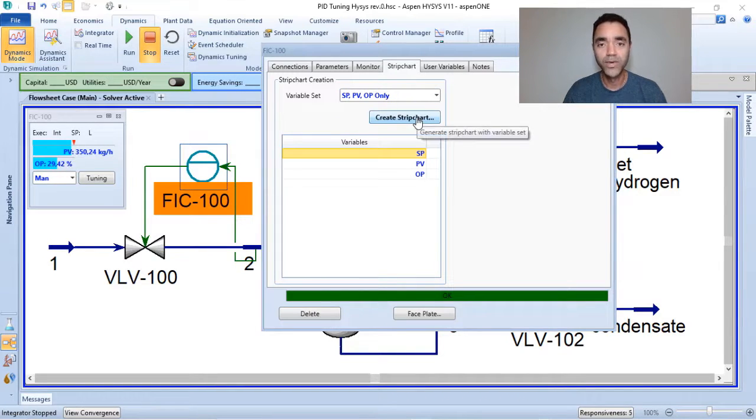It's very important when you are evaluating PID tuning that you observe not only the PV reaching the set point, but also the opening of the valve, because when you are doing a PID manual tuning, observing the behavior of the opening of the control valve, you get the feeling to know if you need to increase the KP, or if you need to increase or decrease the TI, and so on.